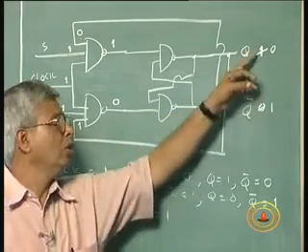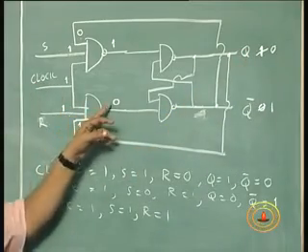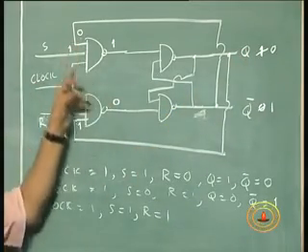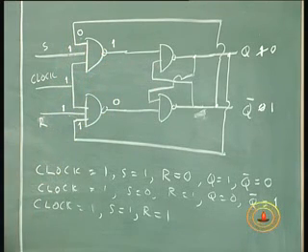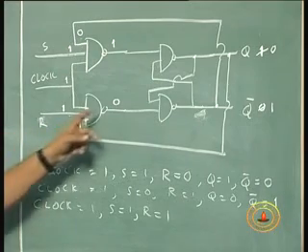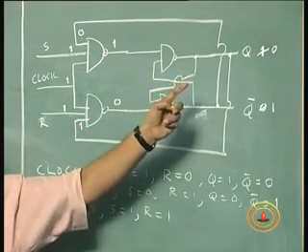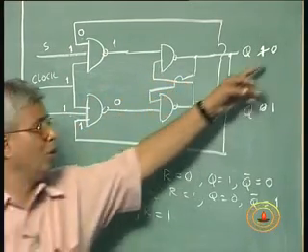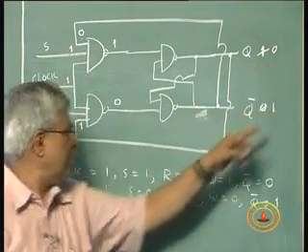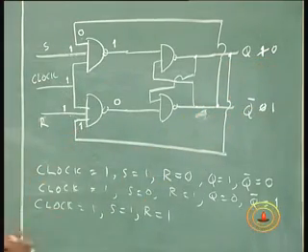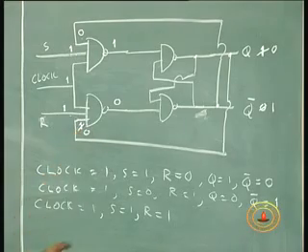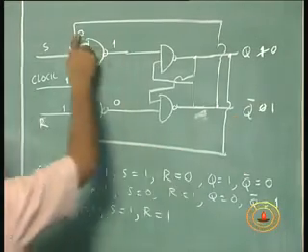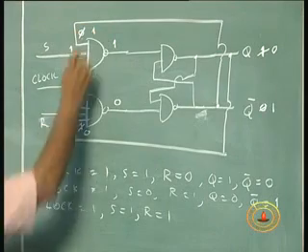This 1 gets reflected here, 1 1 1 gets an output 0, 0 1 1 gets an output 1. So 1 0 at the input of the NAND gate, original SR latch, remember the NAND gate, 1 0 is a reset state, so it's just 0 1. Now this 0 gets back into this, changing this 1 to 0. This 1 changes the 0 to 1.